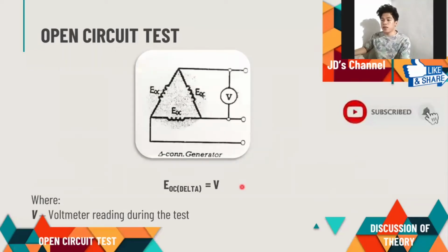And then the next one is if it is delta connected, so the voltage would be equal to the reading of our voltmeter during the test. When it is delta connection, the EOC would be equal to the reading of the voltmeter during the test.